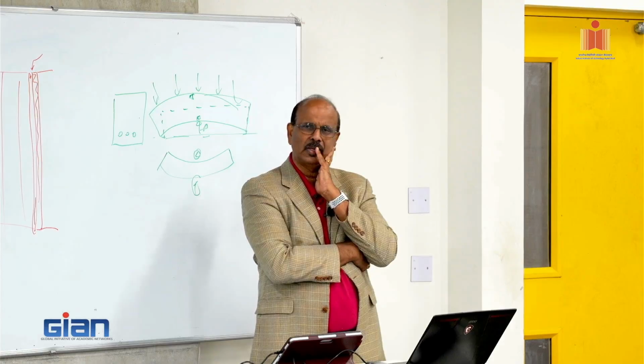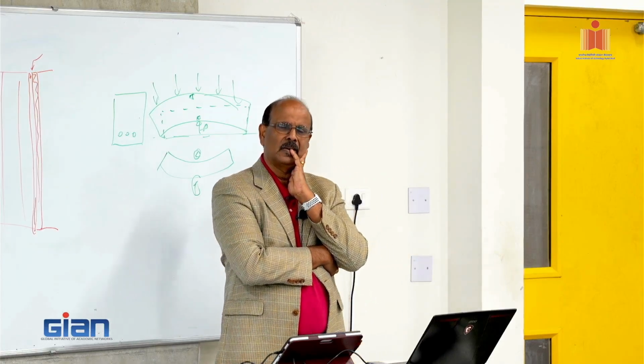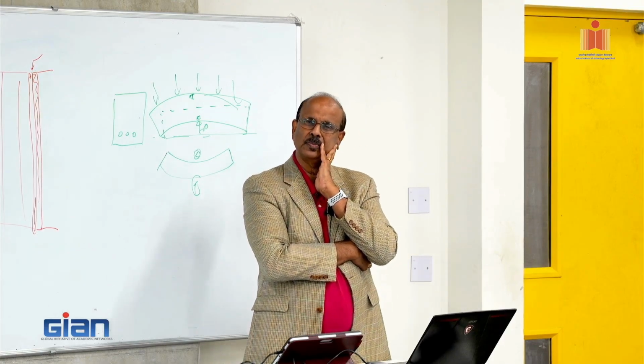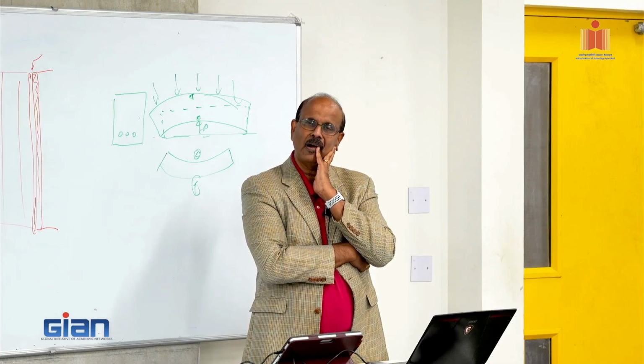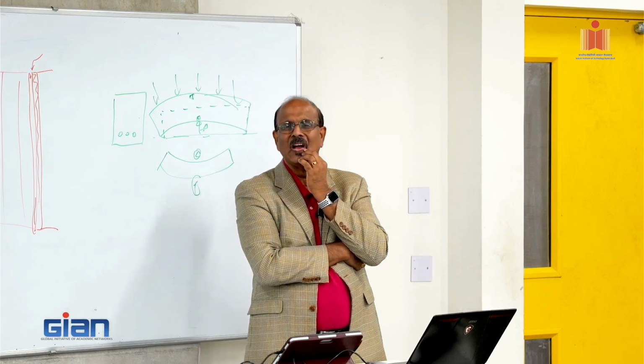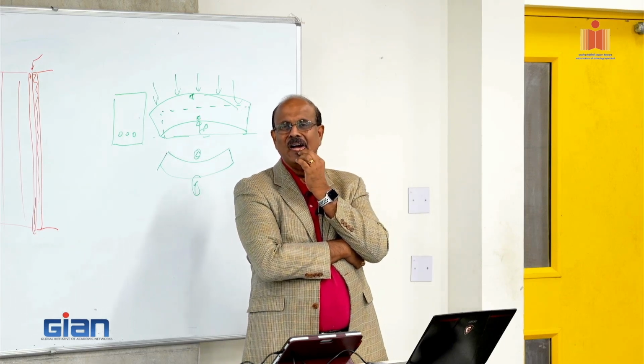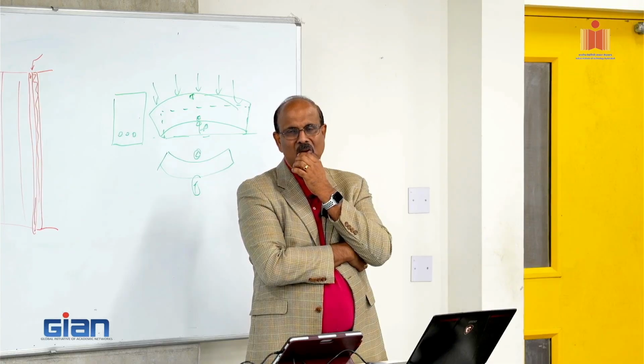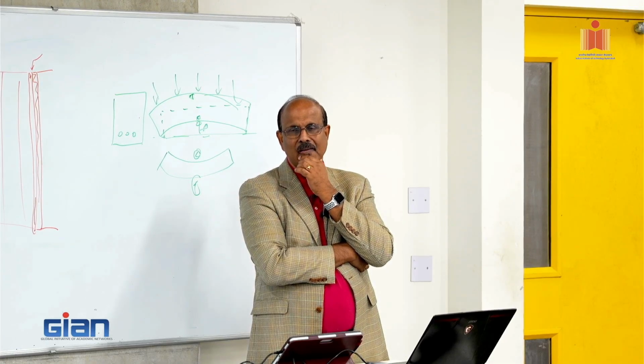Yeah, I don't think it's 24 meters in the US. So anything goes. 40 feet road, sir. All the turning radius with 15 meter, that is 12 to 14 meter, without checking it will turn. Okay. But 18 meter, the erection engineer has to see the turning radius. More than 18 means it's purely based on chance. Most of the site will not allow. Some site, if it is just next to the highway, when the railway is going straight and turning.